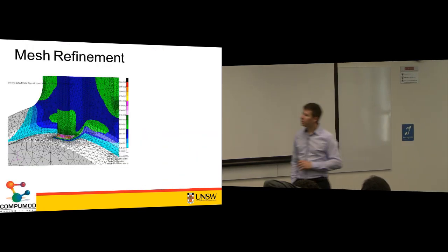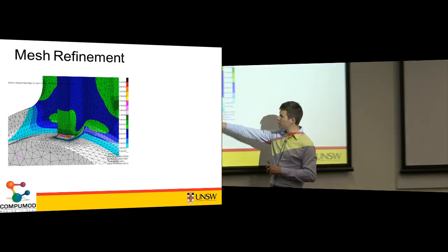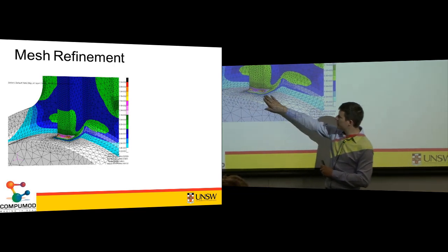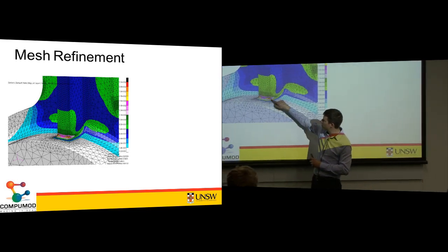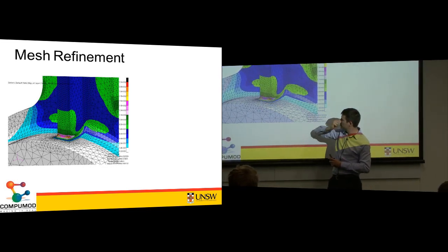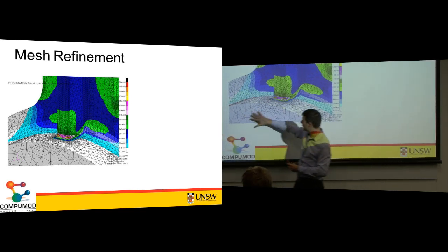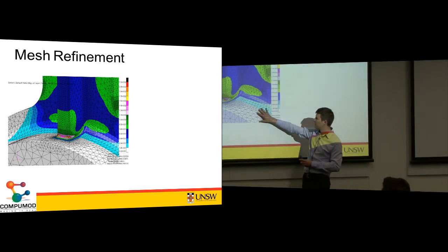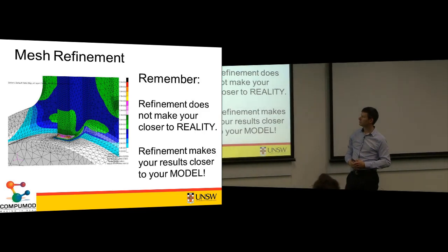We talked about mesh. You want to refine your mesh, so small mesh equals computational power required. You want to refine your mesh around places where your stress changes a lot. So in this case, small mesh around the chamfer, which is good. Large mesh away in regions that we don't particularly care about or where the properties aren't changing dramatically. So that would be a well-refined mesh in those terms.